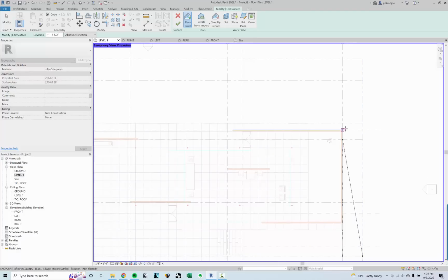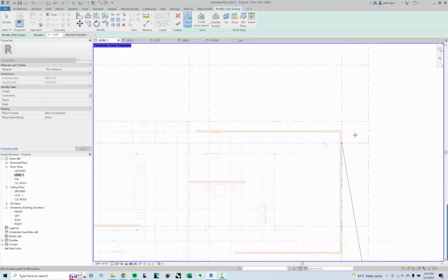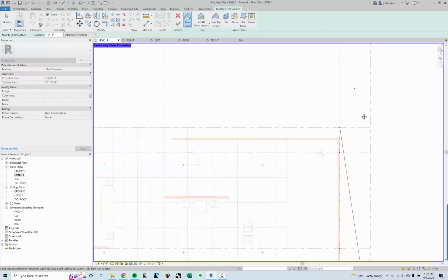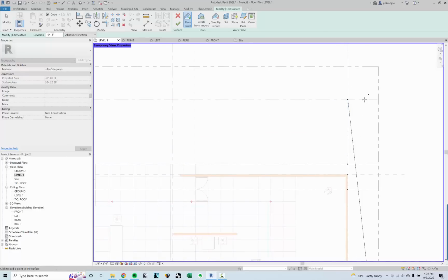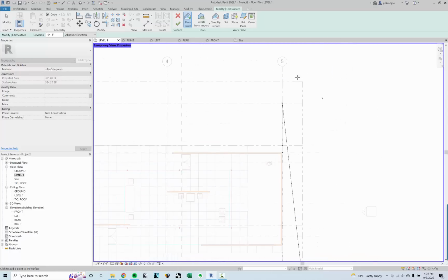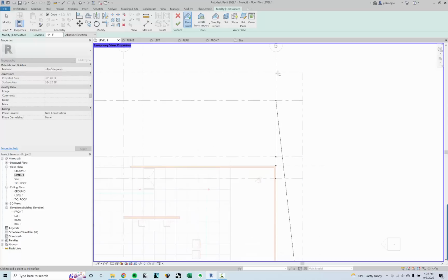Then I have a point at rear grade. This is important because this is where it sort of starts to flatten out. This luckily is -8 inches, and that, and that are all the same place. Now, because I don't have the topography at the edge of this, for the purposes of keeping life easy, I'm just going to carry these over.